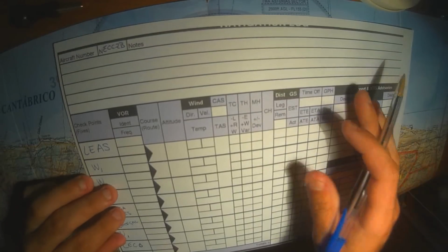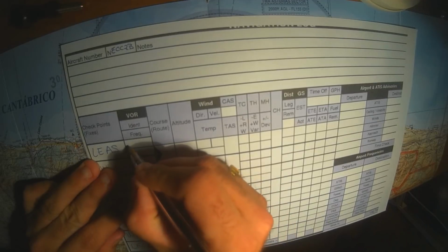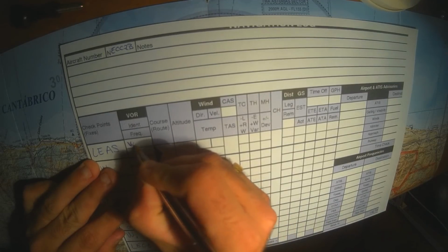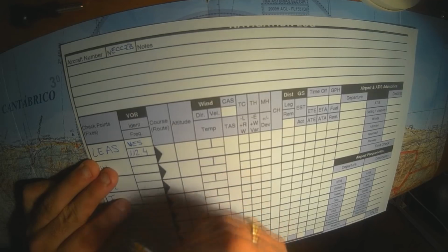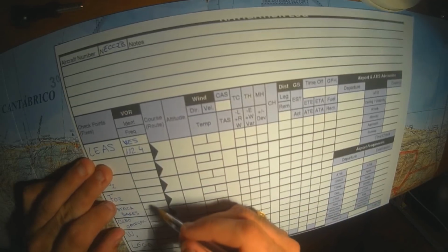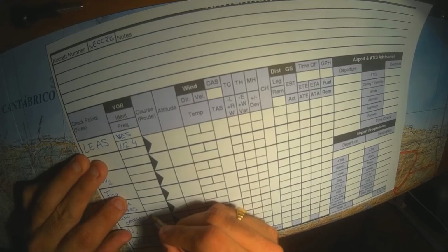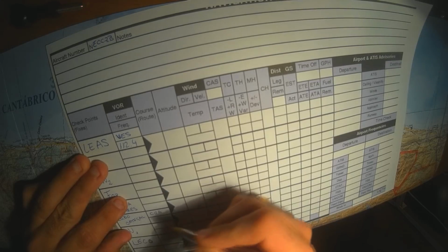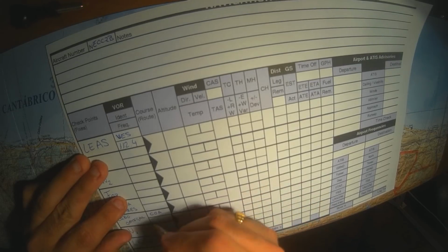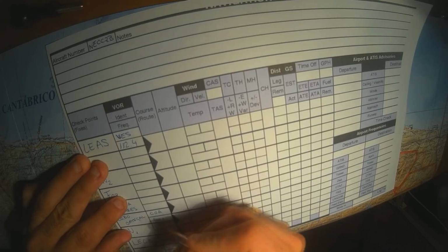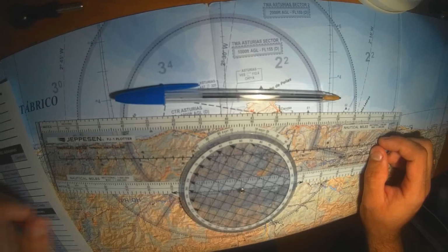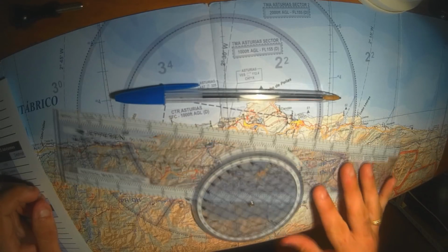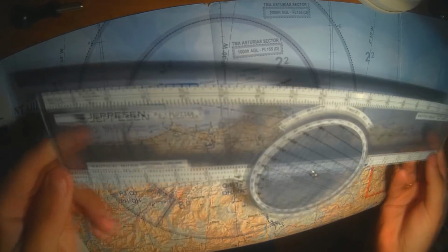The second column is to assist the pilots with any navigational aid, such as VOR or NDB stations. In this case, I will support myself with the Victor Echo Sierra VOR and the Charlie Oscar Alpha NDB and their respective frequencies. Though we are flying VFR, such stations can be really useful to find ourselves or just endorse our navigation. It's now time to start planning our route of flight.